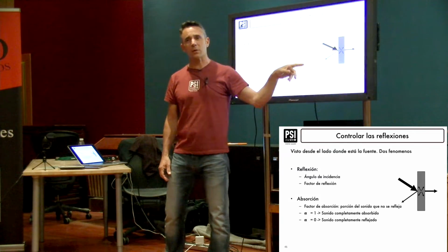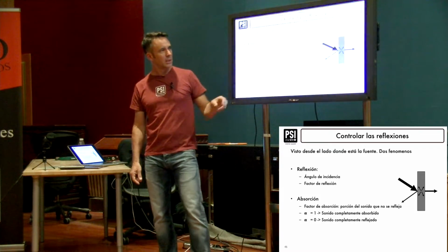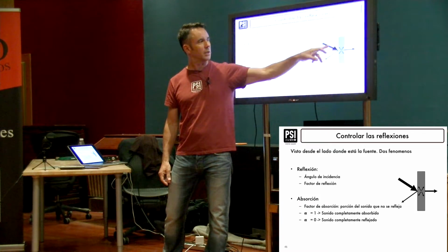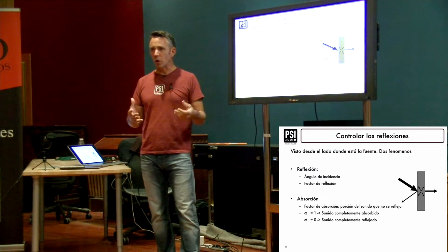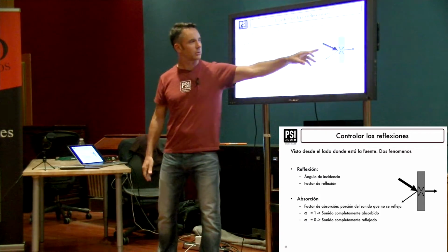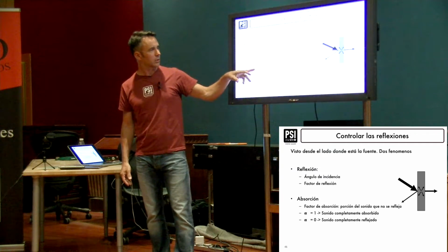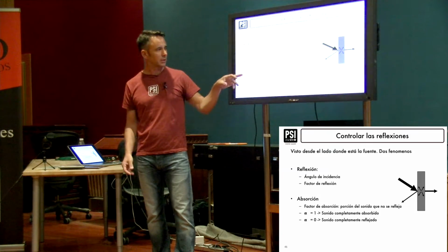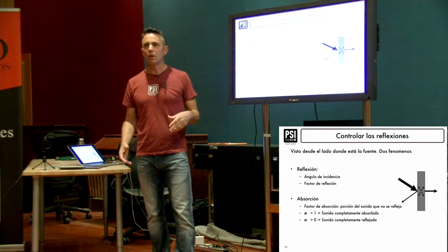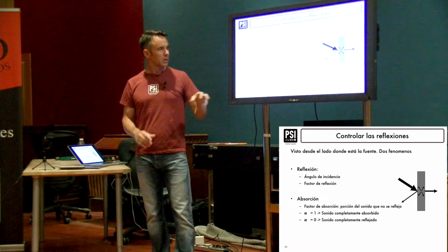We look at just what comes back in the room and what stays in the room, and we'll measure the ratio between this and this to say whether a material is absorbent or not. If it's 100% absorbent, we'll say it's got an alpha Sabine of 1, and if everything's reflected, it's got an alpha Sabine of 0. This I think you're all familiar with.